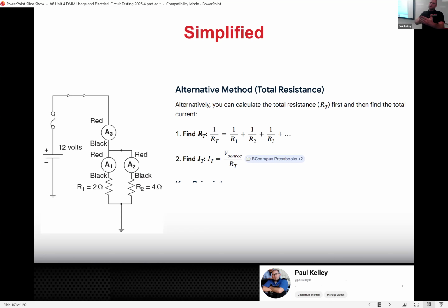So I look at the numbers and it was like, first cylinder was 150, second cylinder was 140, third cylinder was 130, fourth cylinder was 120, and the minimum spec was 135. So the last two cylinders failed. And so they're like, yeah, the cylinders are low on compression. I looked at it, and it was kind of interesting. It started good and it got worse. I interpreted that whole test to be that they didn't have the battery charger on the car when they did the compression test. By the time they got to cylinder 3 and 4, the battery was low. It wasn't cranking that fast. I'm totally convinced that's a misdiagnosis.